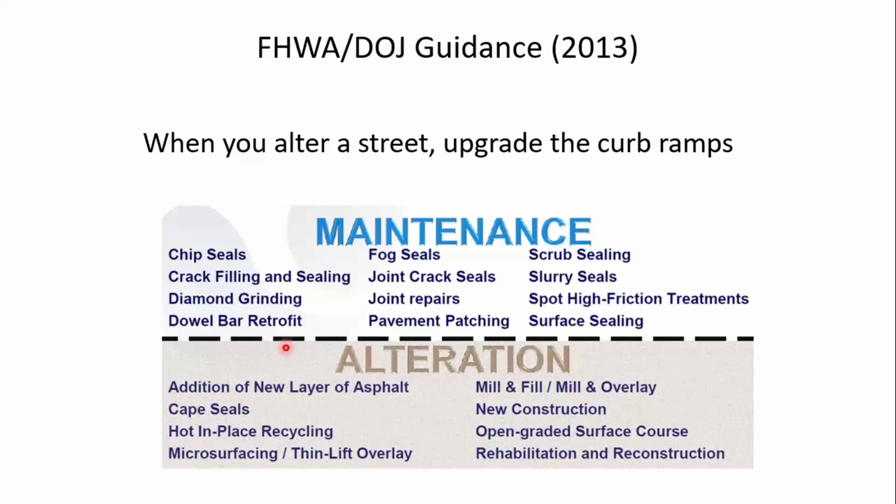But if what you do to your road or street is an activity that falls below that heavy dash line, then it's considered an alteration, and you do need to upgrade the curb ramp. So notice that adding a new layer of asphalt, doesn't matter how thick or thin it is, if you're adding a new layer of asphalt, that's considered an alteration, and as part of that project, the curb ramps need to be brought up to the current criteria.